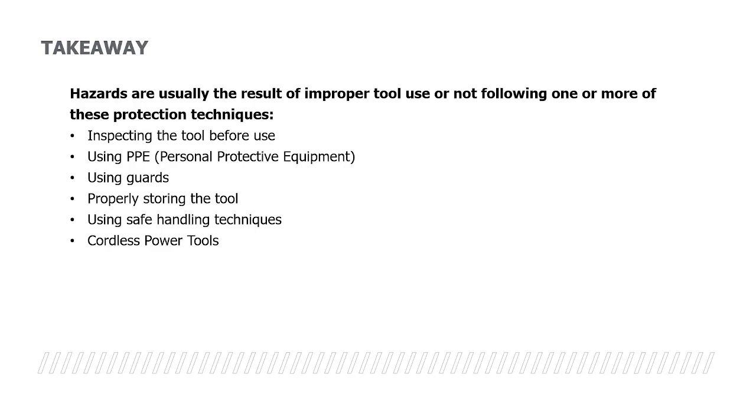Use safe handling techniques. In other words, we don't want to see you carrying the cords and letting the tool just dangle. You need to be carrying the tool, but do not carry it by the cord itself. We also talk about cordless power tools. Remember this: they're very powerful. You don't want to use them in an explosive type of environment. And the other thing with cordless tools is they make so many different makes, models and types of these battery power tools nowadays.